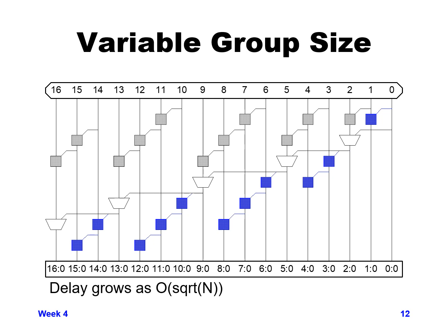And if you do this for larger adder sizes, so if we went up to 64-bit, like I mentioned in the previous slide, the delay will grow as a square root of n. So from 16 to 64 is a factor of 4 growth. The delay in this adder would only grow by a factor of 2. So the 7 stages we have here might go up to 14 instead of the 21 that we calculated. So this is a decent way to take the carry skip design and improve on it and get even better delay through your stages.